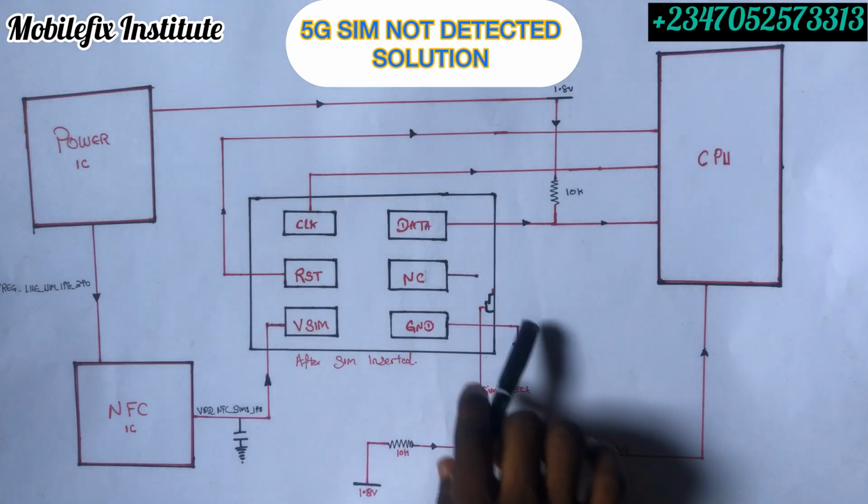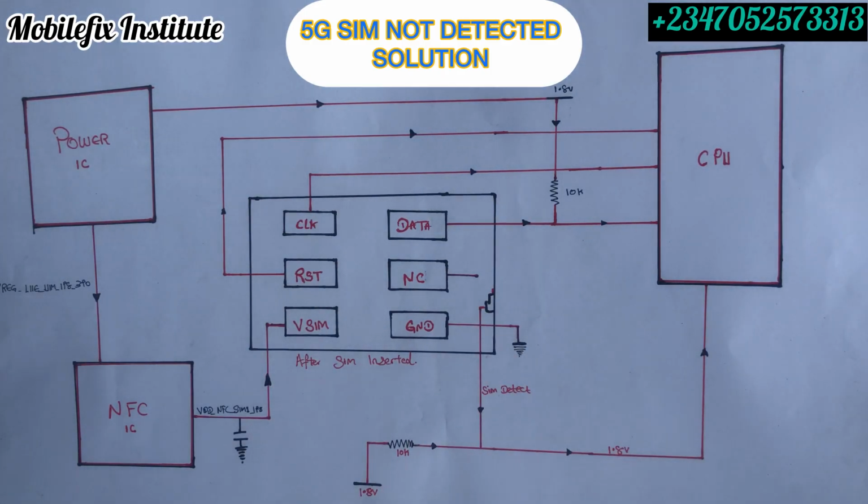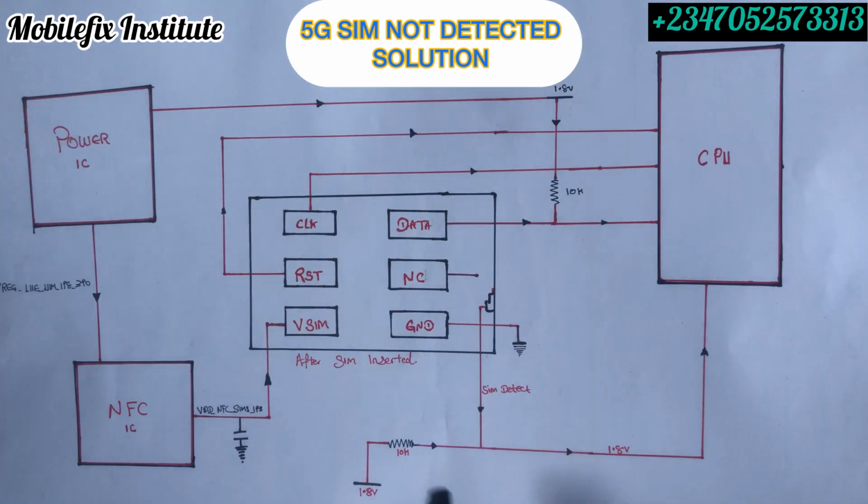But when you insert your SIM card tray, it will disconnect this pin from ground, and you will have logic high. Now this voltage will flow through this line. Now the CPU will be able to sense that something has happened. Let me tell you how this works. Now 1.8 volts is coming from your power IC, and we have a 10k resistor, a 10,000 ohm resistor here.